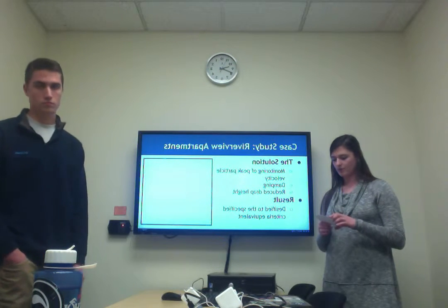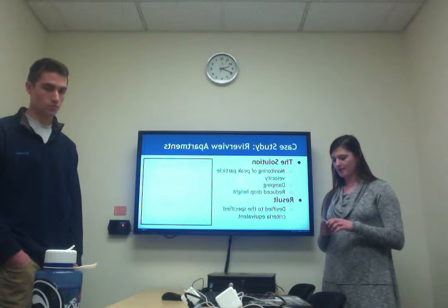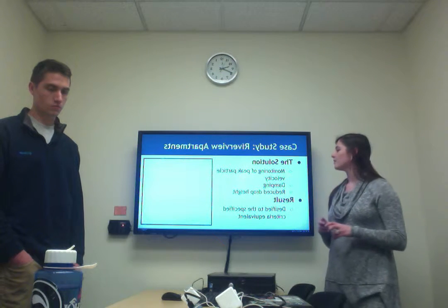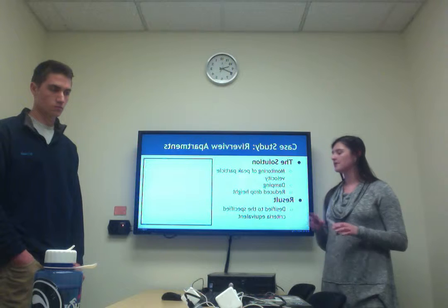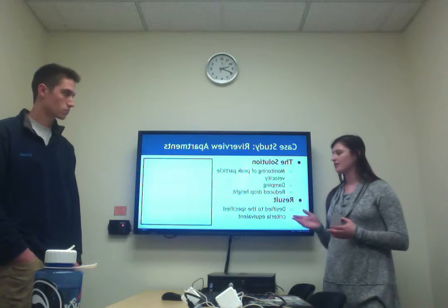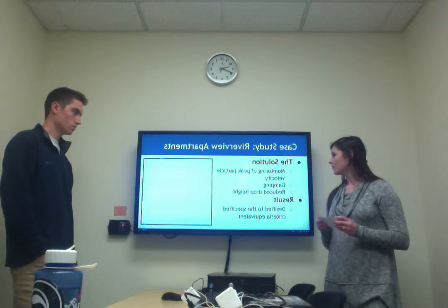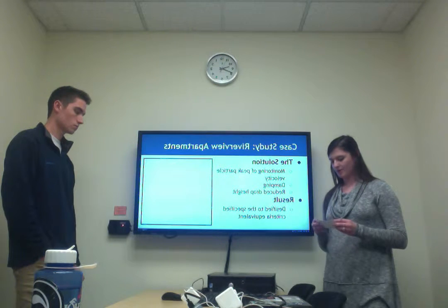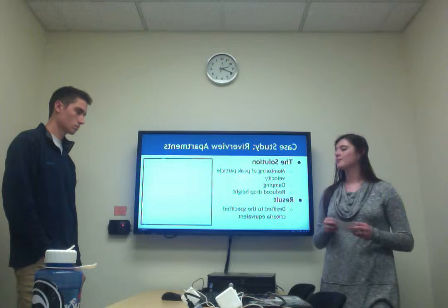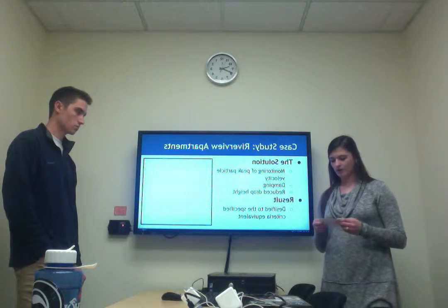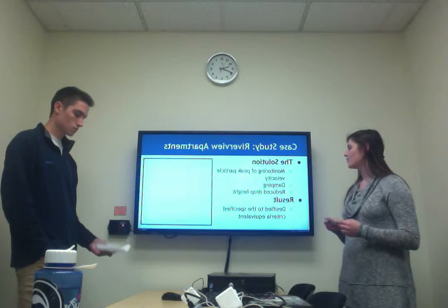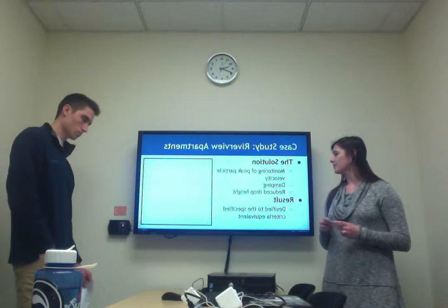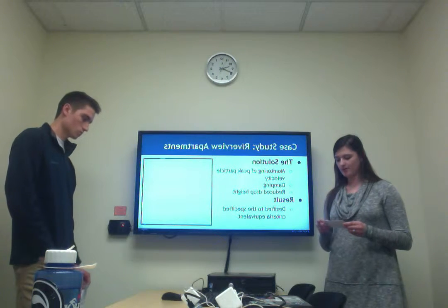So they had to excavate the pipeline to make sure that it wasn't being affected because it came within 25 feet of the site. So after testing it, they realized that because of the rigidness of the pipeline, damping occurred, and it actually only had 1/2 of the waves that were occurring in the soils next to the pipeline.